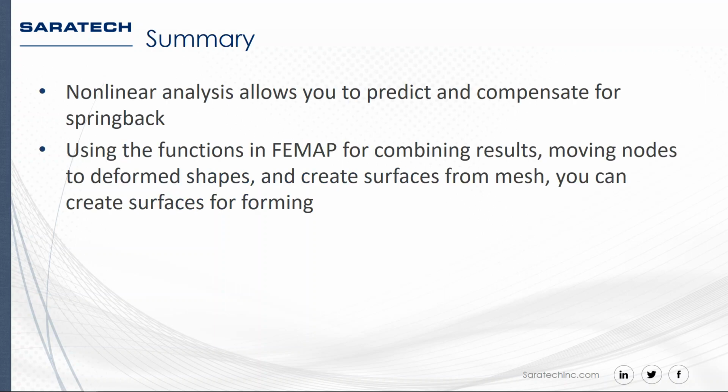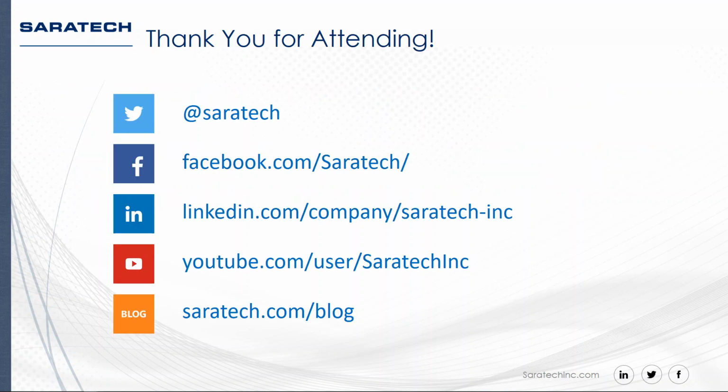So in summary, nonlinear analysis allows you to predict and compensate for springback. Using functions in FEMAP for combining results, moving nodes to deform shapes, and creating surfaces from mesh, you can create surfaces for forming that are compensated for the springback. That's all I have for today.